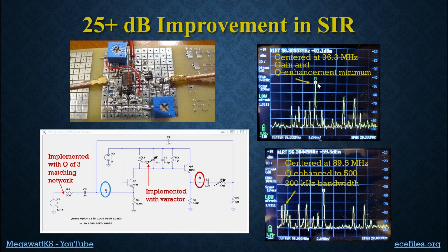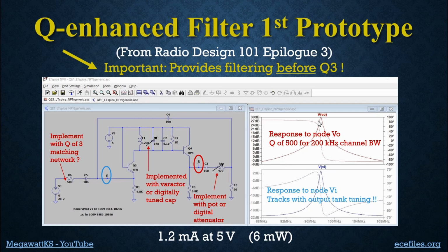That's no problem. What is a problem is trying to receive these signals down here in the lower end of the band. Notice they're essentially right at the noise floor. But if we retune the center frequency using our varactor diode with this potentiometer, and we increase the positive feedback by cranking up this guy, which actually cranks down this resistance, then we get that peaking here.